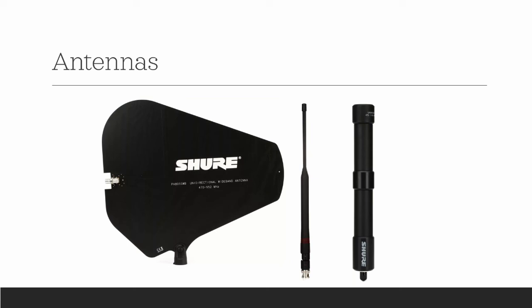Or you see helical antennas, which unfortunately I don't have an image of. Those are always cool, definitely something to look up on Google if you get a chance. Same sort of thing, much more directional, and you benefit from a little bit of added gain by being directional. They also make active directional antennas, which have an amplifier in them, and you're definitely getting a lot more gain from those. What I'm referring to is a little bit different, but it's neither here nor there.